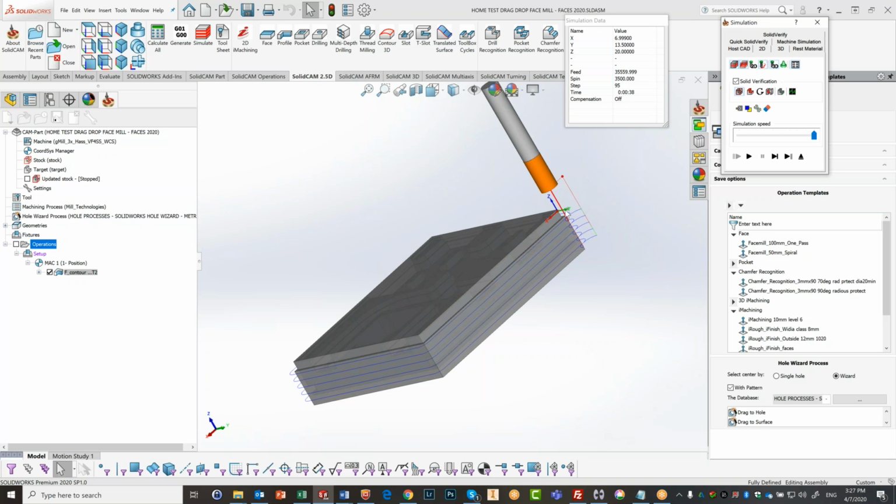But let's say my geometry was from here just to here. If I wouldn't go up to my clearance level and stay down here, it'll actually cut across the part and ruin the part. Therefore, it goes up by clearance. However,